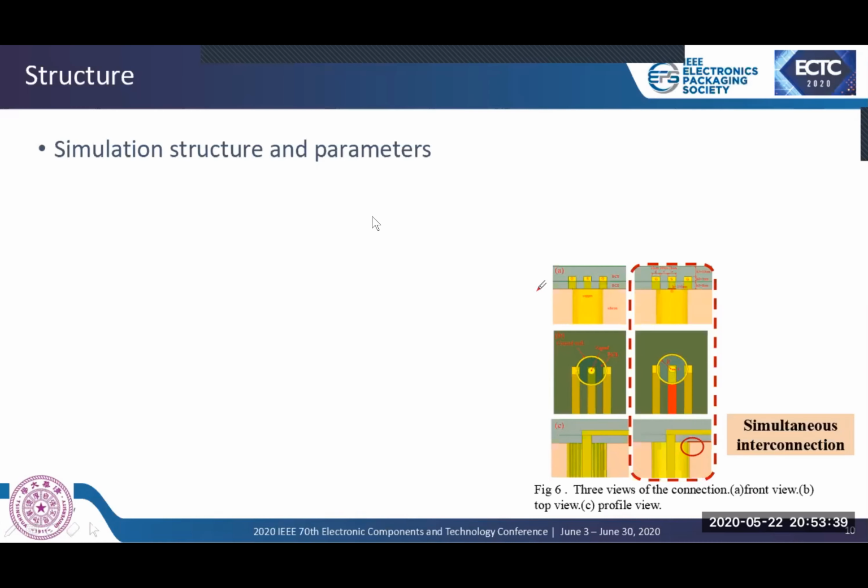From the top view, the diameter of the signal and outside ground are 9 micrometer and 36 micrometer respectively. These values are based on the software TXLine and optimized through simulation.